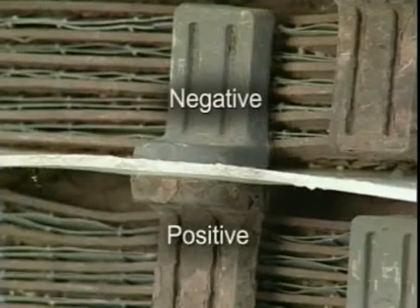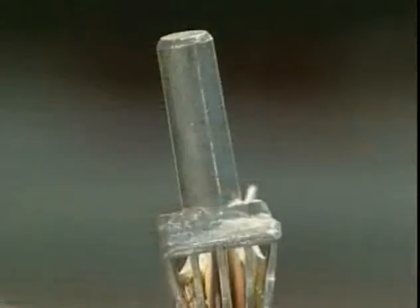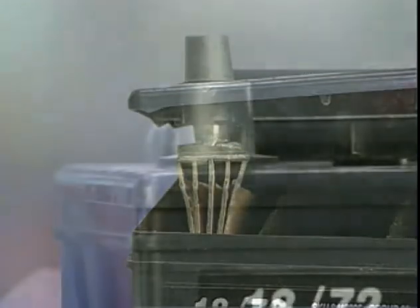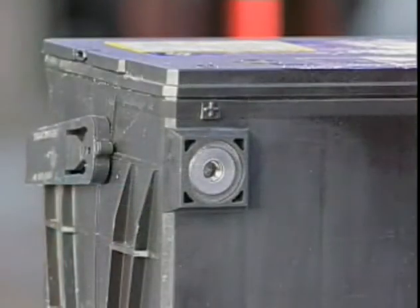The positive plate straps of one cell are connected to the negative straps of another, thus supplying a series electrical connection. At the positive end of the battery, the positive plates are connected by a lead strap to the external positive terminal, while at the negative terminal, the negative plates are similarly attached. The terminals themselves may be located on the top of the battery or on the side.